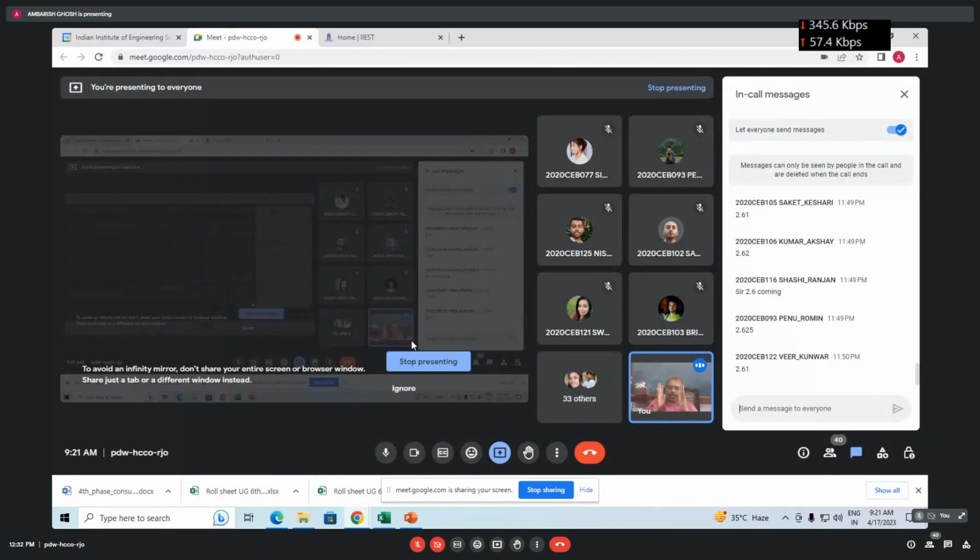So for a given soil profile, as you know, the top layer is coming in the picture, and you have got the depth of fixity, so that is contributing to the lateral load. So you take the proper parameters, either eta h or k1, table 3 or table 4. Then you calculate either T or R. Then you get the value of LF by R, or LF by T from figure 4.